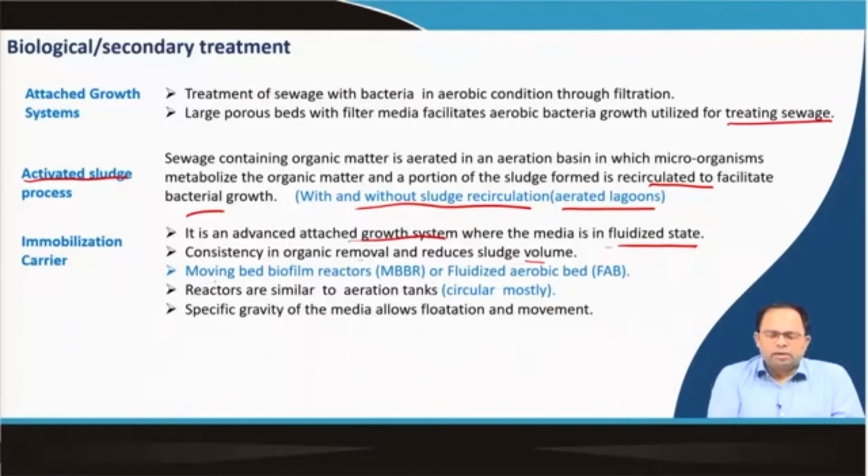There could be one technique, moving bed biofilm reactors, MBBR, or fluidized aerobic bed, FAB. So, there are different technologies involved, which have variations of designs and so on. But roughly we understand that it is an attached growth system, where we use filter media, but instead of the filter media being fixed, it moves around in the sewage.